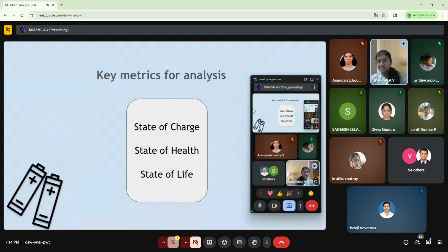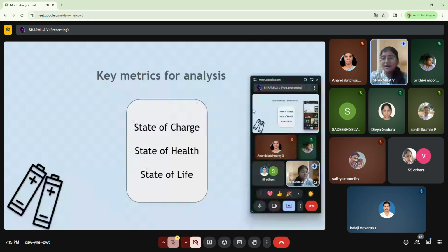Having this data incorporated in the entire electronic system will give an alert if a certain parameter exceeds. Let's say if the temperature exceeds some degrees Celsius, or if the voltage rating exceeds some limit, then you can simulate alerts to notify the user that the battery is overheated or is going to fail soon. Based on the alerts, we can save the device by cutting the power supply given by the battery to the device.